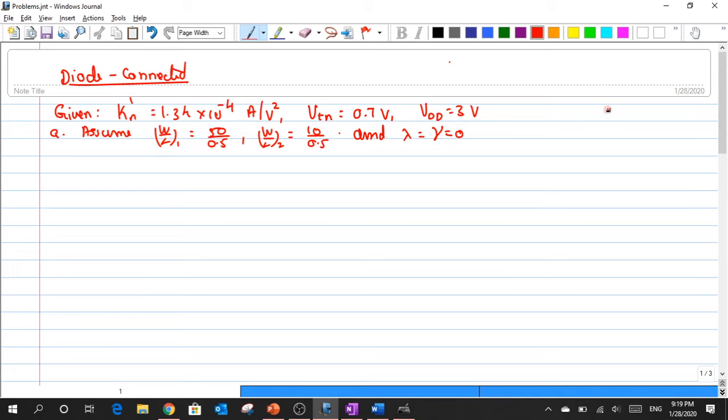And the circuit that we are going to use is a diode connected structure with NMOS as the load or the diode connected device, and the input is again connected to one more NMOS structure, and I'm tapping the output across the drain of M1, which is V out.